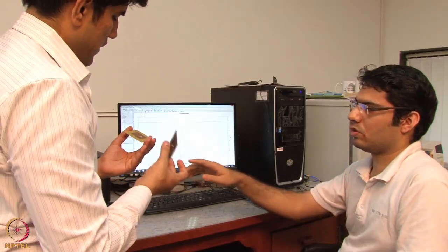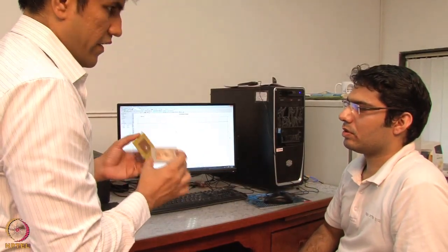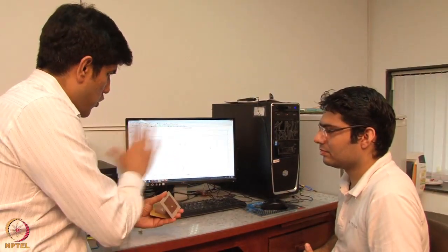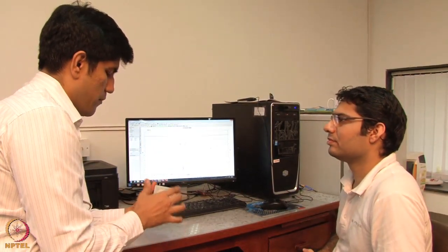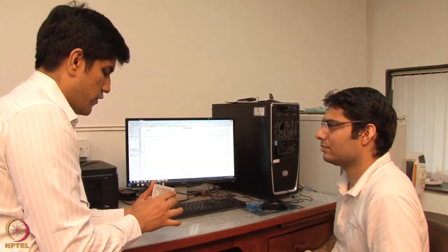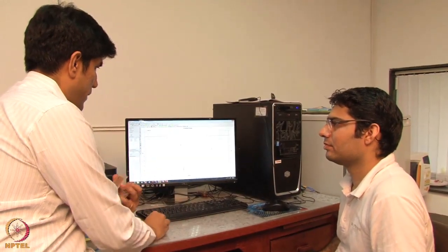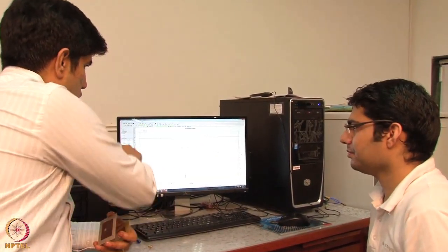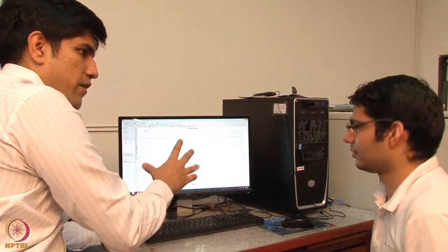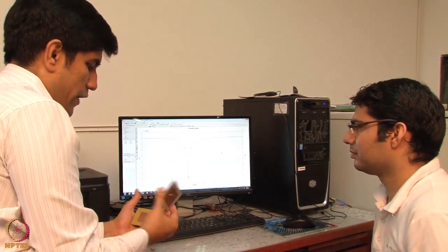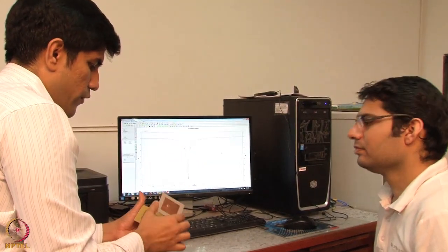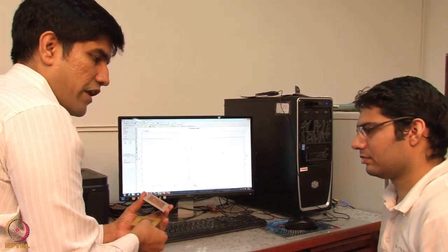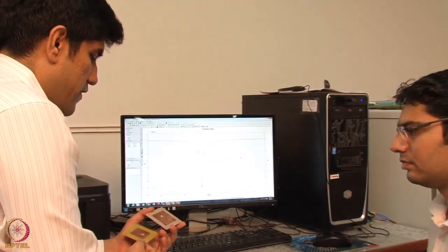Okay. So basically, this is going into the basic electromagnetic theory of modeling antennas. From the methodological point of view, you have used the method of moments to compute this, and you also explained we are taking 501 points, whereas what we see here is not 501 points. It's randomly choosing some points. And again, you explained different materials, how you can improve the S11 parameter, or the minus 10 dB loss aspect of the antenna itself.